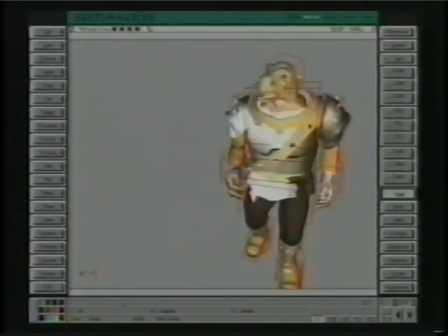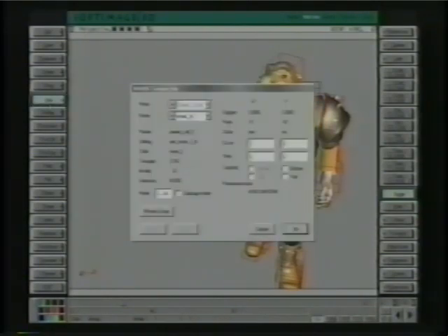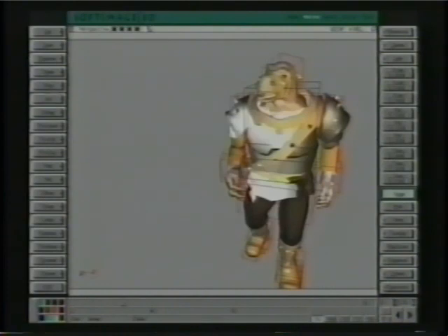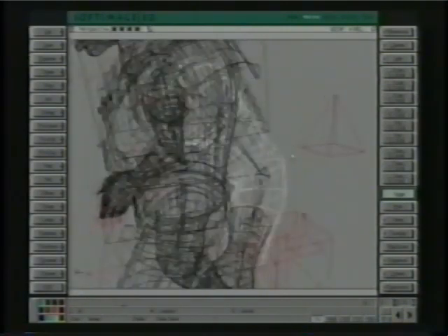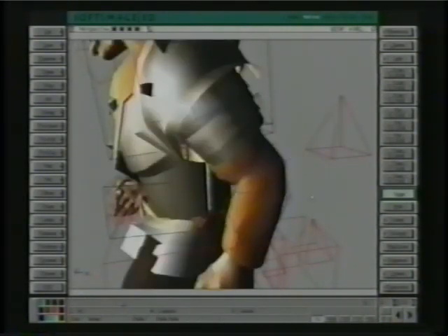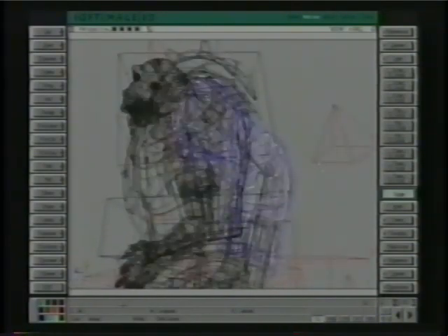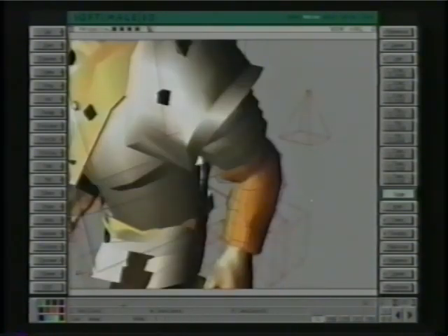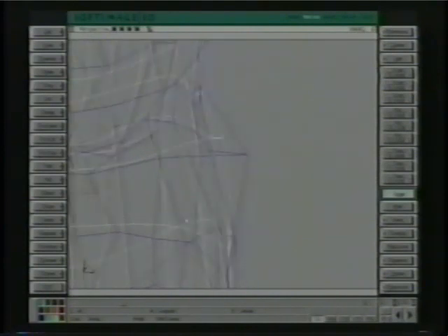Now another display optimization trick. If you notice that each NURBS or patch object, if you go into Info Selection, you can see that it has a step, and you can increase that, decrease that, increasing or decreasing the resolution of the patch. Let's take a close-up look at that. Turn on the lines. So this is how many points it has, you can see, and then in between all the points it has only 2 steps. If I turn on wireframe mode, you can see that a little better.